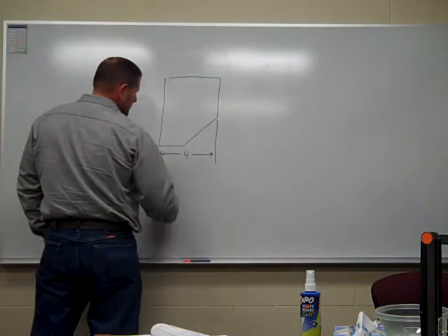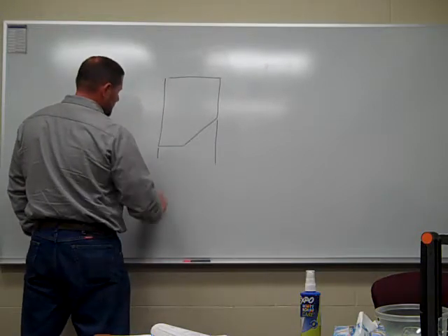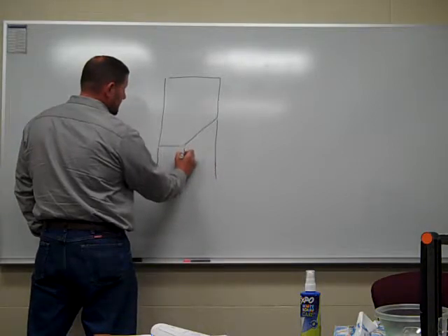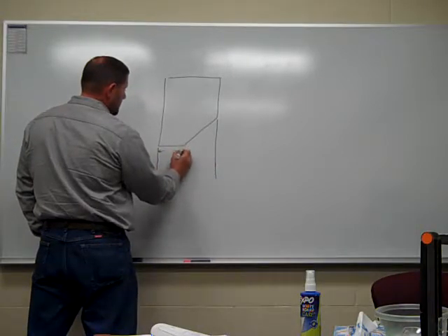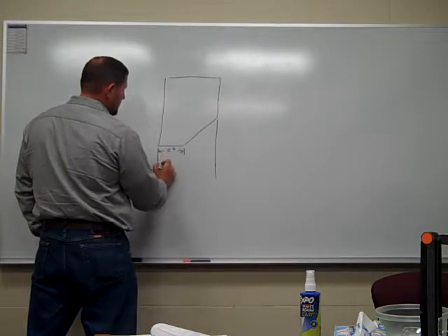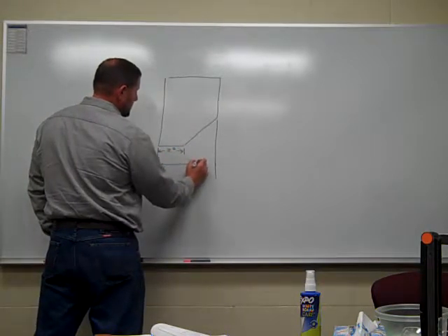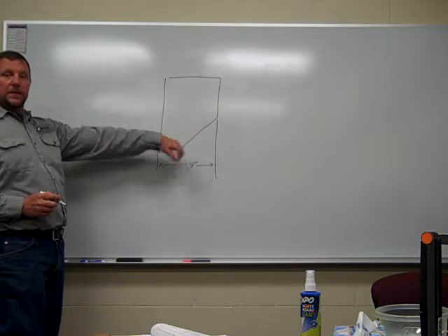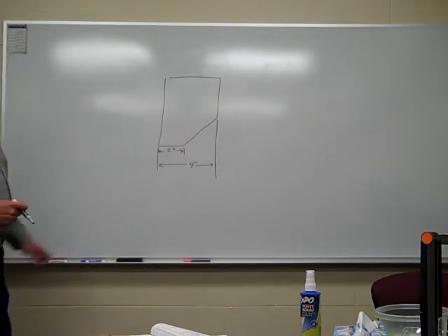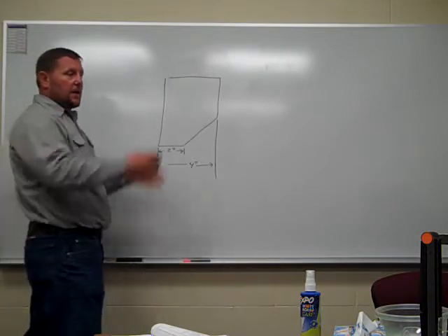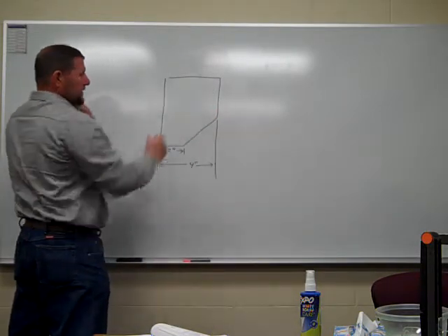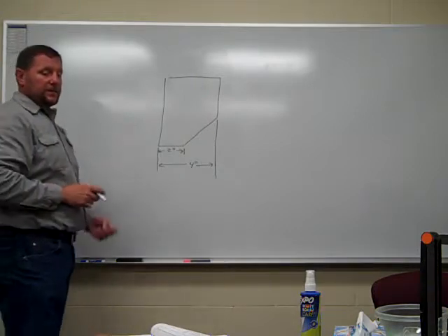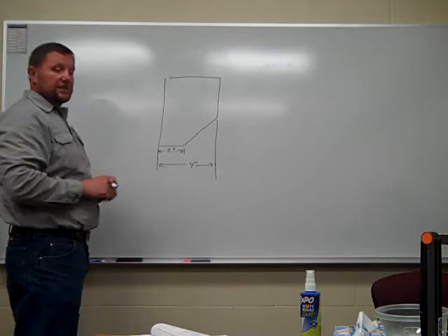Another way to show this, we can use extension lines to do multiple dimensions. Here's another extension line here. Let's say this is 2 inches. Overall length of that object is 4. So your extension line can be used multiple different ways. But that's what it is. They're used to dimension prints or extend a line out to give you an actual measurement. Any confusion with that, like I said, contact your instructor and he'll definitely go through it.